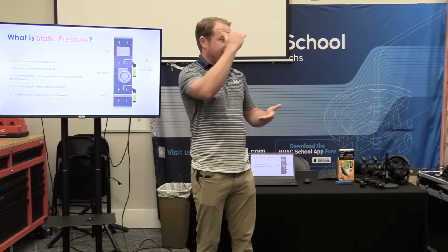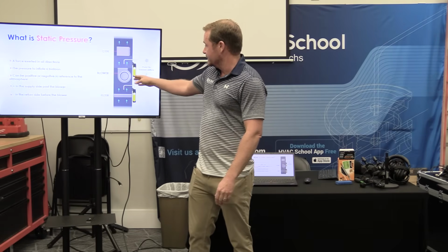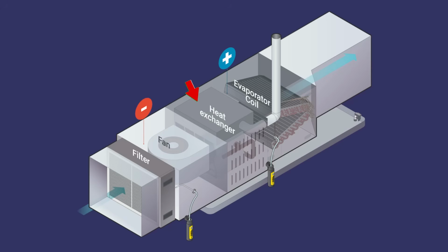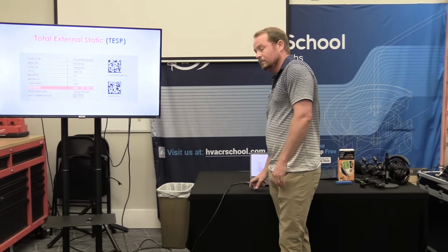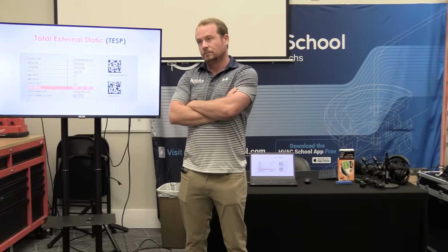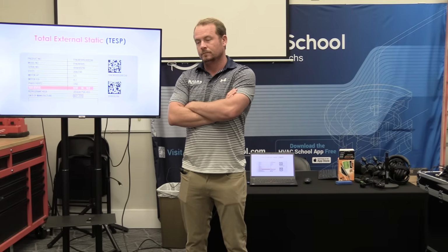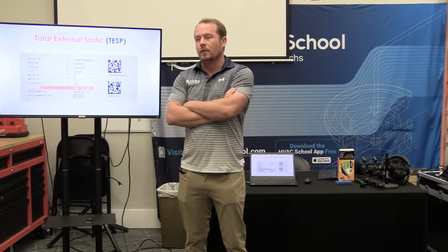So in the case of a fan coil, what comes in the box is the blower and the evaporator coil, right? In the case of a gas furnace, you have the heat exchanger and you have the blower, but you don't have the evaporator coil. So you have to measure the coil pressure drop separately. Would that be the same for a heat pump that comes as a two-piece system? Have you ever seen certain manufacturers where the coil and the blower are two separate pieces, you can screw them together? No, but I think that's still going to be one model number. Okay.